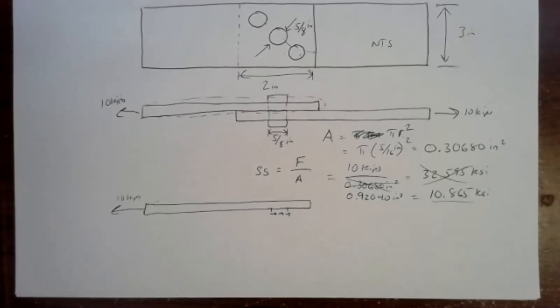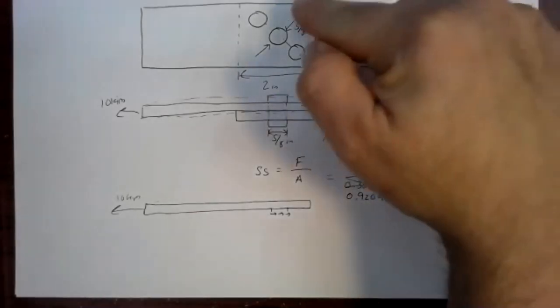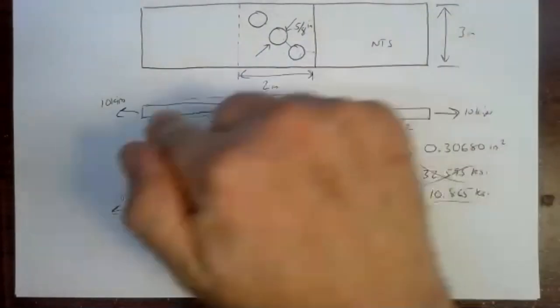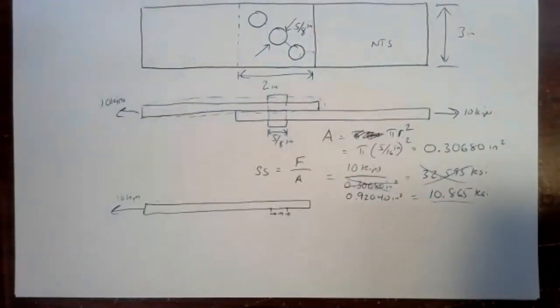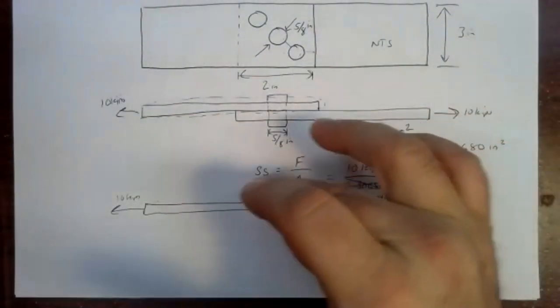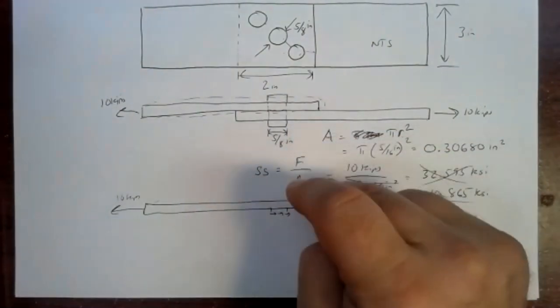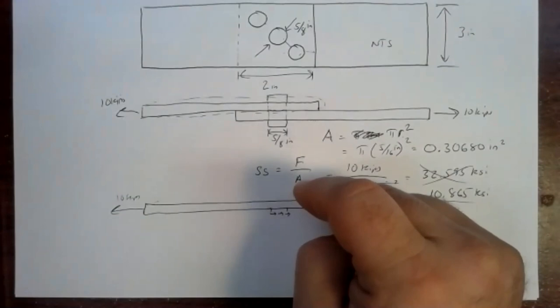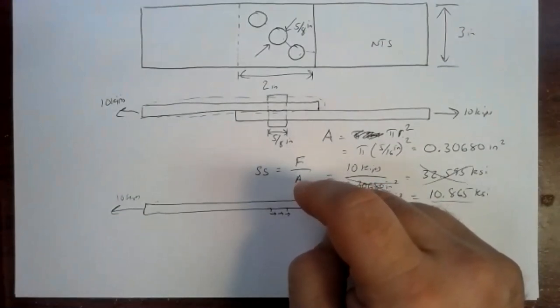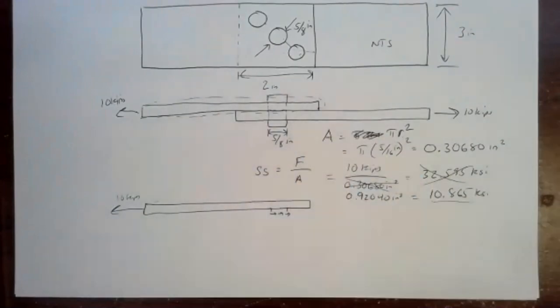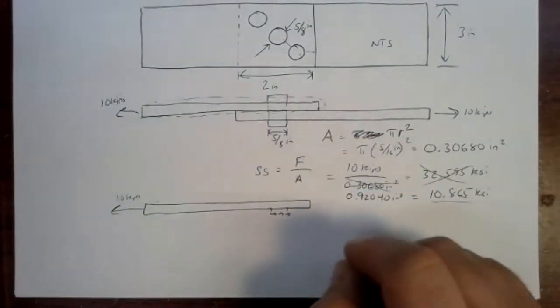the shear stress will be right. In fact, to give you a little bit of preview of what we're going to do on Monday with shear stress and rivets, we'll have this lap joint, we'll have how much force we need, and then we'll say, here's the shear stress the material can handle. So from that, you can figure out the minimum area of material that you'd need. And then you'd have to ask the question, well, how many rivets would that be?